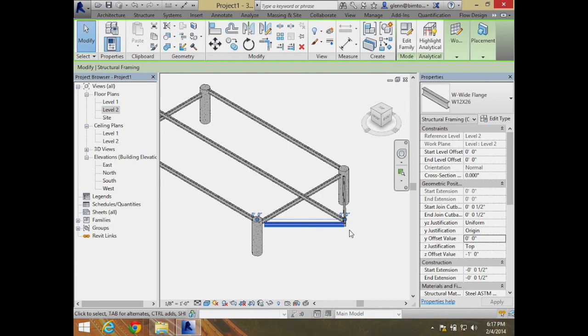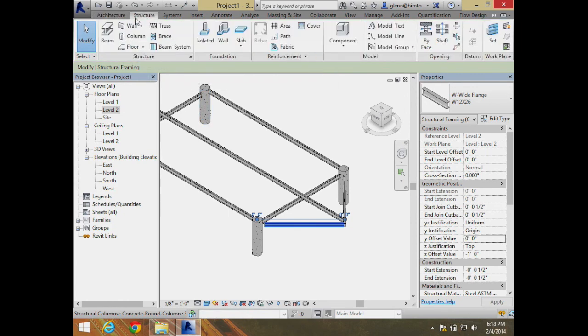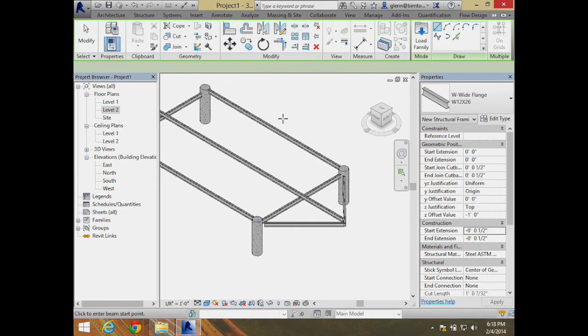Okay? So same sort of thing. We'll play all sorts of funny framing tricks in terms of if you have atria, if you have different sorts of openings between the floors. The big rule on most openings is that if you want to create an opening, for example, I want to have some atria between these different floors, the most common thing you'll end up doing is something like this. I'll take some structural beams, and we'll go from here to here. I have my levels a little wrong now. I'll fix that. Up to there.